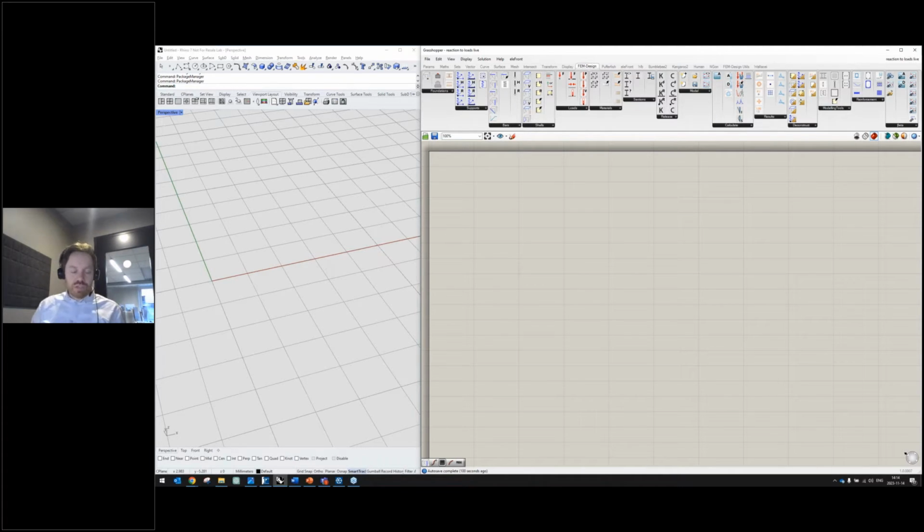So in this example, we will use a deconstruct method to open up an existing model and make changes to that or read results from that model. So let's start by initiating a connection with a FEM-Design instance. And you can do that from the group called beta over here. It's a new tool, so that's the reason why it's still under development. So it's a beta version, but it works well. Soon we will also have a full version of this, which works perfectly in all situations. It works great now, but it's still under development. So that's the reason for the beta.